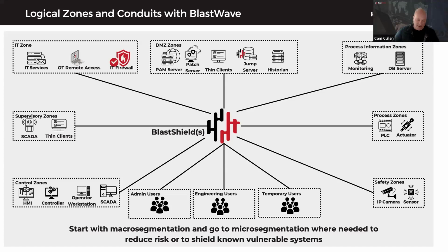Yeah. I mean, at the end of the day, if something has network connectivity, there is no physical segmentation possible, because they have to have logical. Now you could say, I need to put a gap between the process and maybe the DMZ and other things. So there are places where you may have to put those gaps. And again, there's nothing wrong with saying within the OT network, I have logical separation. Maybe that blast wave is not allowed to connect out to the rest of the world. So I would have a physical gap, so to speak, or an air gap in that case.